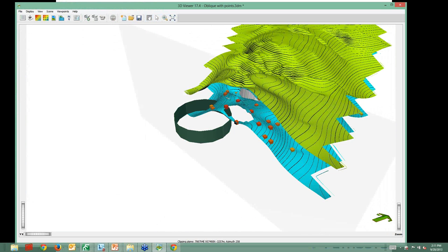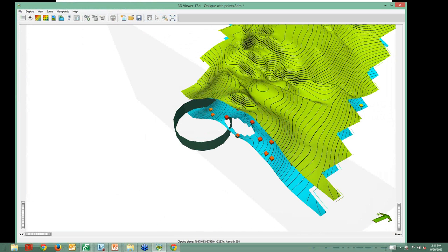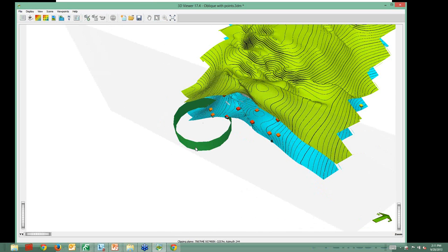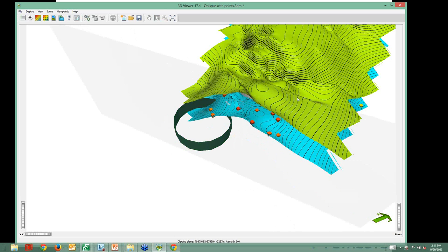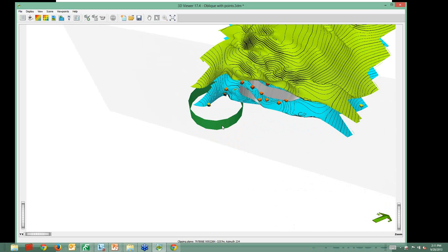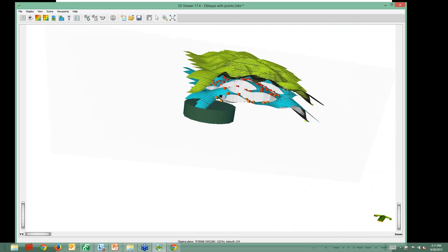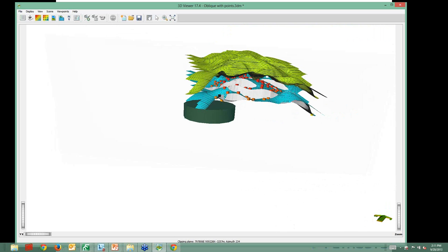What this is really handy for is, first off, I can now make my cross-sectional view totally perpendicular to the structure, so it doesn't only work with north-south or east-west directional trends. What we could also do here is line that up to, say, the direction of the fault plane, and then move that in there so it basically overlaps with the faults. And now I can view a cross-section along that plane and compare my multiple grids.